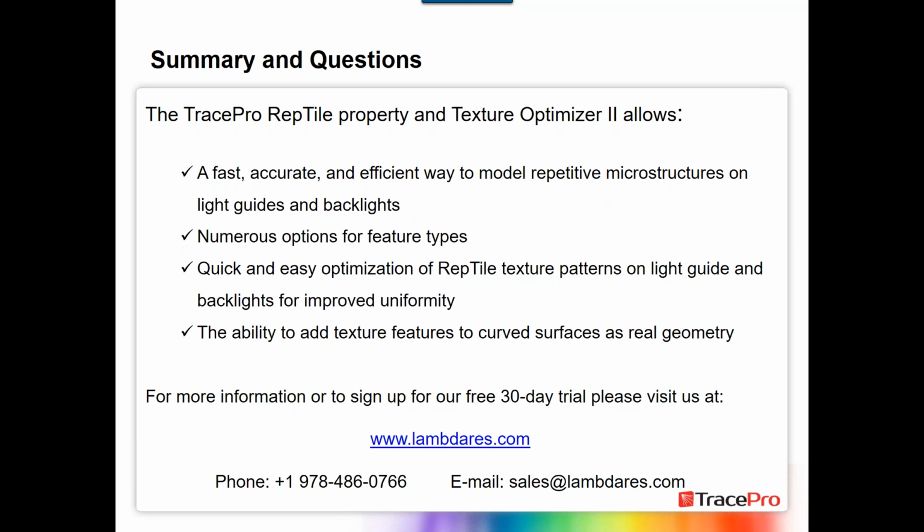I'm not sure on the exact equation that's being used to calculate the error function. I can take a look into that, but basically what it's doing is looking at the irradiance in each of the cells in the irradiance map, comparing it to the density of the cells for the texture, and adjusting the density to adjust the irradiance values. And I think the error function is just the difference between what uniform irradiance would be and what the simulated value is.